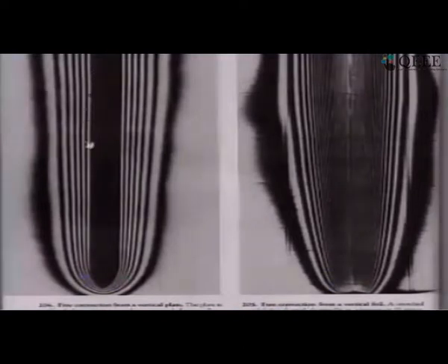So this was the bright fringe, and then there's a parallel dark fringe, and so on. So this fringe pattern is exactly similar to what I have just drawn, and this is the bottom edge of the plate where you can see that these are joining and going up. So it tells us not just qualitatively but sometimes quantitatively also what is the thickness of the boundary layer and how it changes in the vertical direction. It is getting slightly thicker. You can see that. That means that the local heat transfer coefficient is decreasing in this direction. So this confirms what I have just drawn for an isothermal plate.